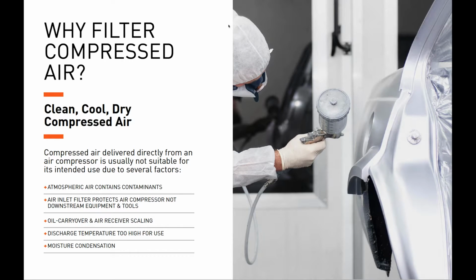We can see that compressed air treatment is critical in ensuring an efficient and effective compressed air system. Contamination such as dirt, water, and oil will deposit on the inner surfaces of pipes and fittings, causing an increase in pressure drop. A loss of pressure is a loss of energy used to compress air. In addition to satisfying an application's particular compressed air requirements, dry, cool, clean air most likely always results in lower operating costs. DV Systems' DF series air filters effectively reduce contamination in your airstream while maintaining a low pressure drop, ensuring your compressed air system delivers clean compressed air to your facility.